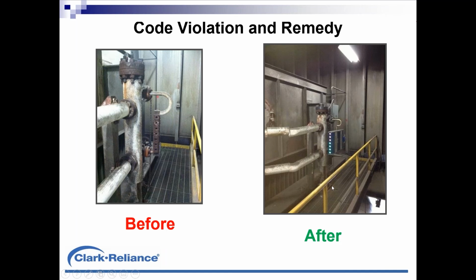So when you look at the after photo, we retrofitted a new gauge. It's outfitted properly. I'm probably about 15 to 20 feet away from the gauge taking that photo, and you can see 4 green and 3 red, and we've got a bright overhead light here, kind of making those colors look a little lighter, but no doubt it's easy to read where that level is and very safe for an operator passing by.